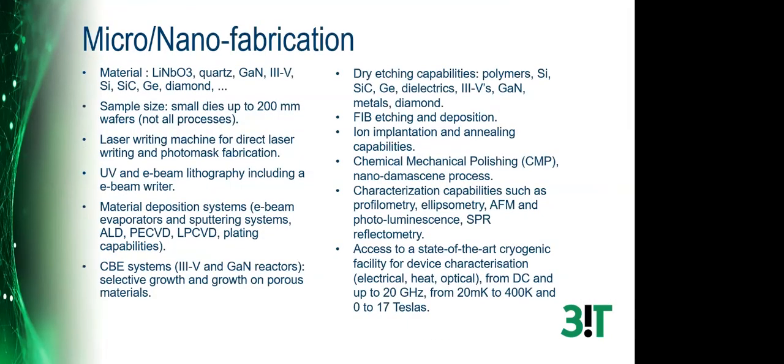So the building blocks, the processes that we use to build up a device, while someone was asking about gallium nitride, we process gallium nitride and make gallium nitride-based transistors in our fab. Actually, we process any material that we feel is non-contaminating. So if we feel a process or a material will contaminate, either we don't process it or we limit its usage to a specific subset of the lab to limit contamination. We can process small samples up to wafers up to 200 millimeters in diameter.